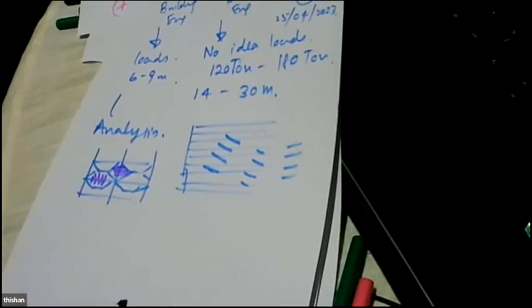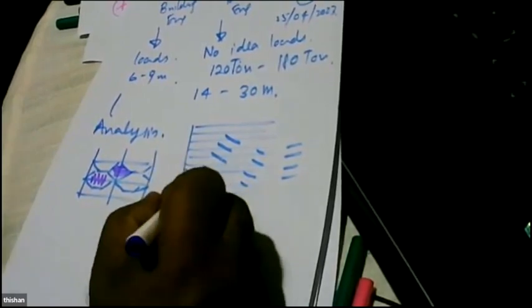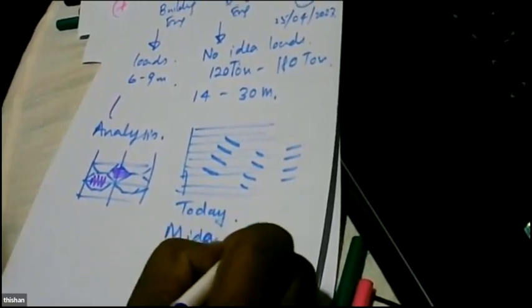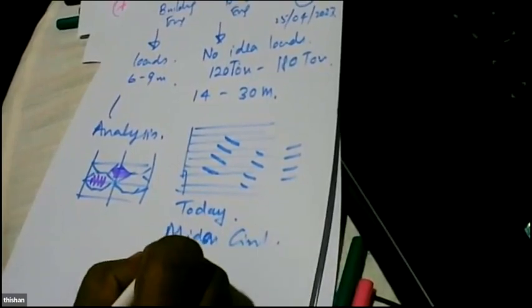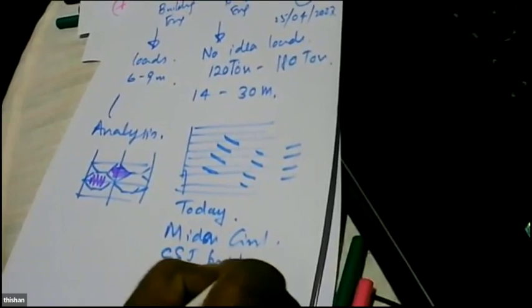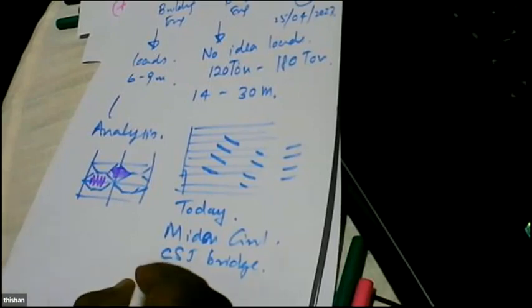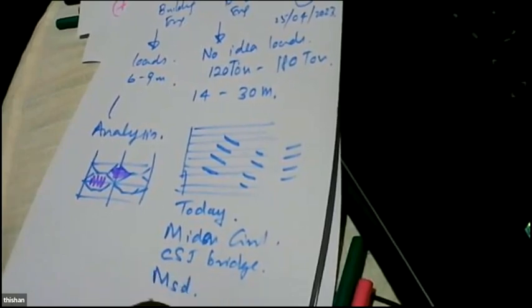But that's the way engineers have been trained. So there is well out of time. But today, if you look at Midas Civil or CSI Bridge, you can specify some loads and very easily get the answers. And sometimes, this can be even automated. Like, you can ask the program to find the maximum moment. So program will try all different types of positions and find the bending moment, which allows you to find MSD and MN.